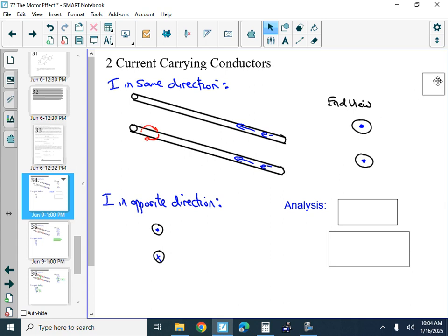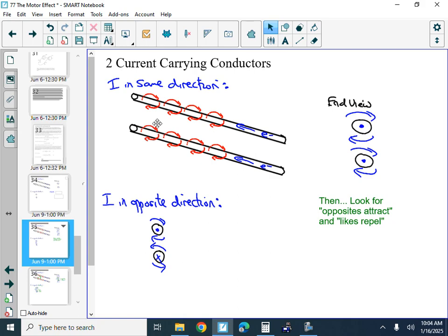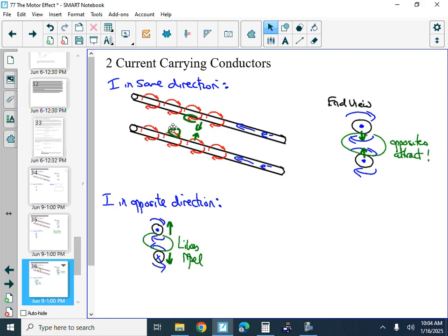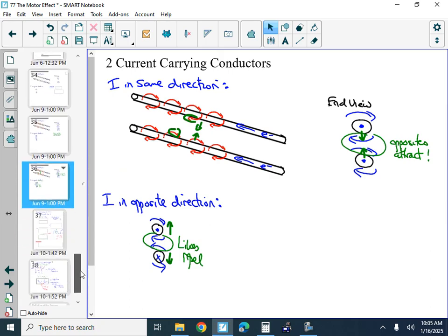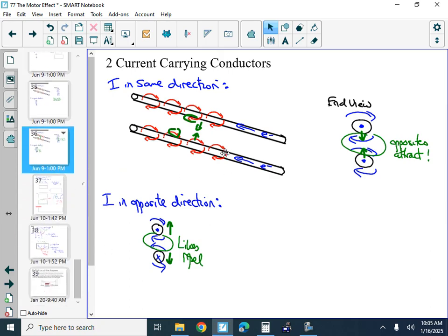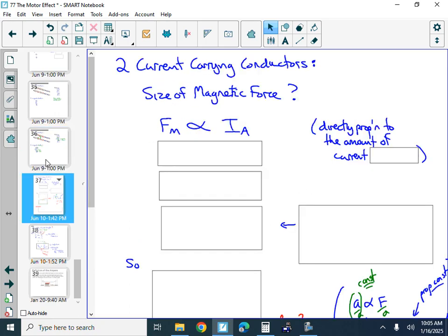If you picture the magnetic fields on these things, in the middle we'd have opposites. This one's down, this one's up. And so there'd be an attraction between these wires. If you had two current carrying conductors, you could actually have a situation where there'd be an attraction between the wires. So, you know, it's really sensitive, fragile circuitry. You kind of have to engineer based on that, right? Have them designed so that you're not going to have a force on the wires causing them to break. So it could be a concern in fine electronics, really. If you have enough current flowing and wires side by side, there's a real force there.